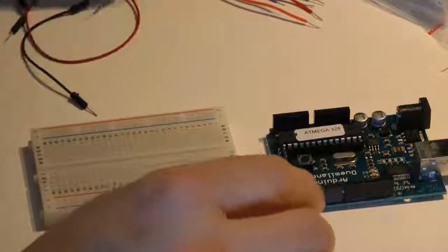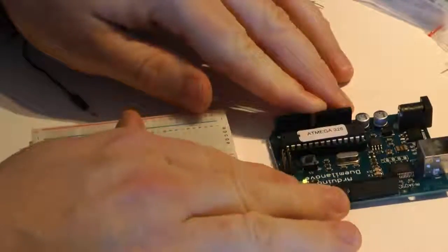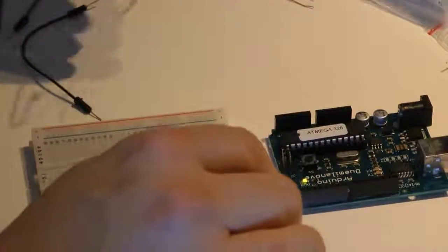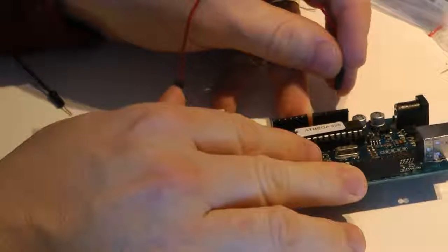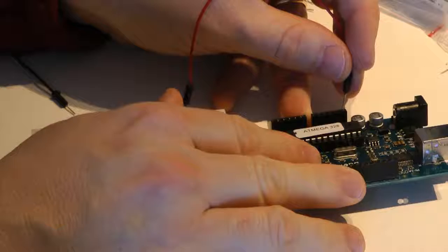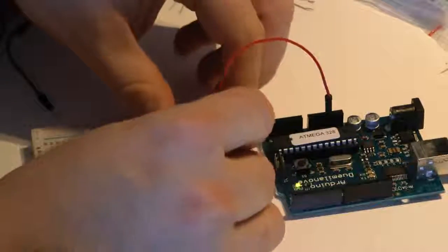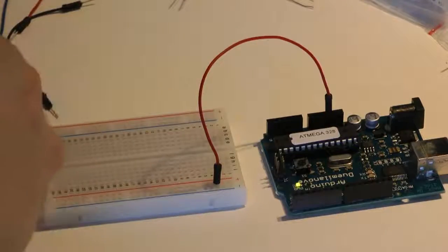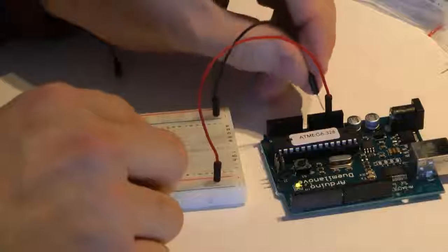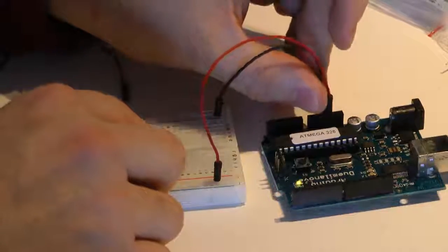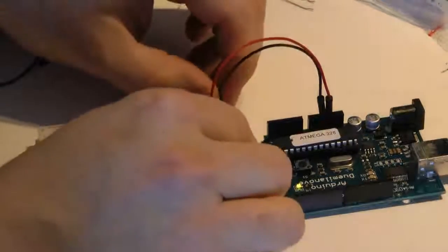Okay, so one of the things we need to do is get our 5-volt power. Like I showed you in the video, it's the third over from the left, so we go reset, 3.3, 5-volt. So I plug 5-volt into the 5-volt power rail, and then ground into one of those ground ports. Right next to the 5-volt is another ground port, so I could plug it in right there. So that's plugged in. Now we have power for this.